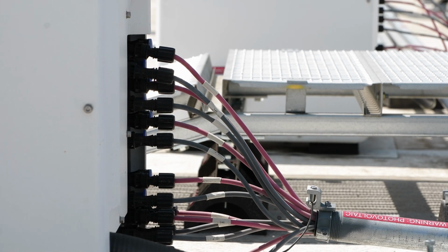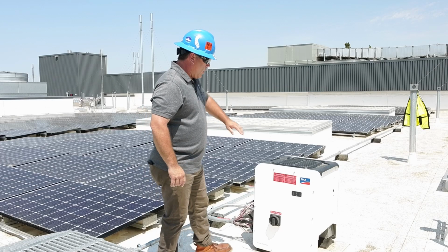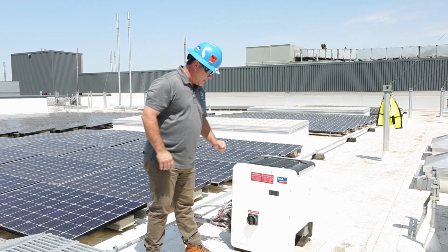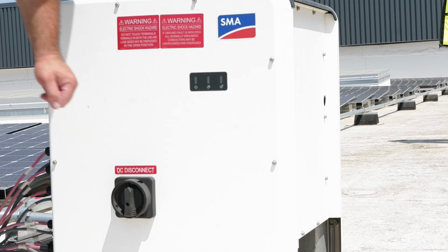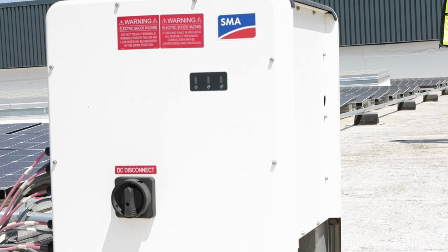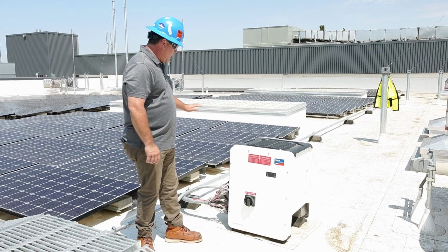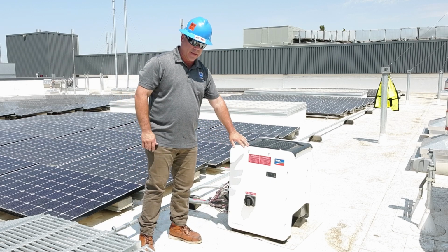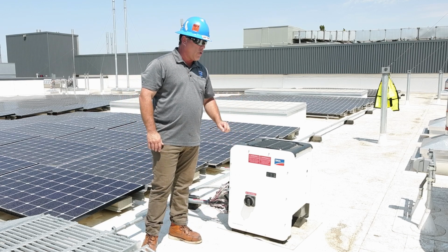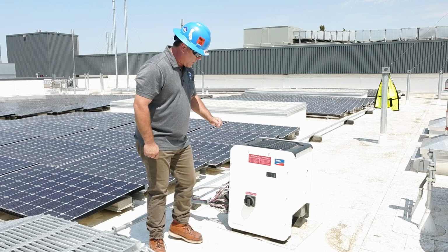And we have our DC side. We're looking at the opposite side of the AC disconnect. We have the DC disconnect here. When we activate that switch, when we turn it off, we're disconnecting the grid, the solar panels, from the inverter. So if there's anything producing, we'll turn it off. Nothing is going to go through inverter. Nothing is going to go back to our source.